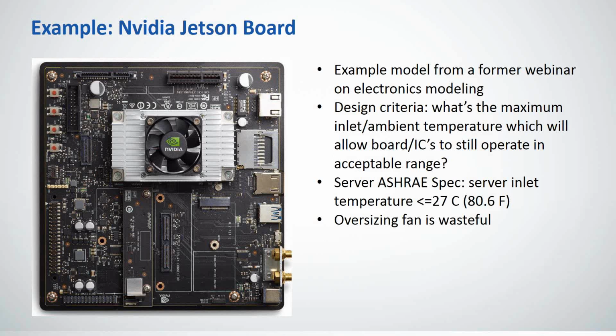I have a little experience here in the data center business, so I know rack inlets on servers have to be under 27C, that's the ASHRAE spec there. And nowadays, just oversizing fans or over-engineering it is kind of wasteful. So you might want to understand what kind of environment a board like this can operate in, and when things really go south.